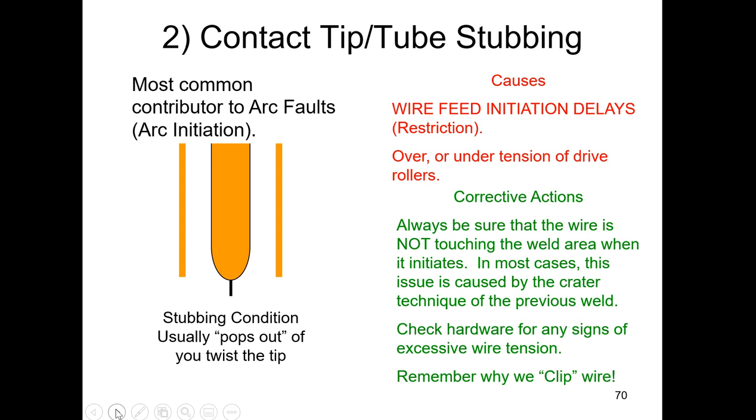But take caution with that cute little feature to make sure we don't touch that next weld surface before the contactor pulls in. Because if you run it too long, there's usually a timer involved, it'll make a larger ball. Remember, the larger the ball, the bigger the silicate island on the back end of that wire is going to be. Because silicate islands show up on the wire the same way those little bits of glass are all over our regular gas metal process.